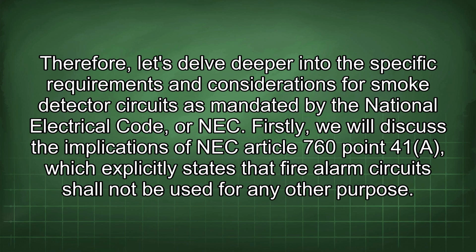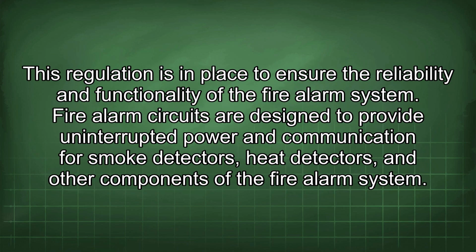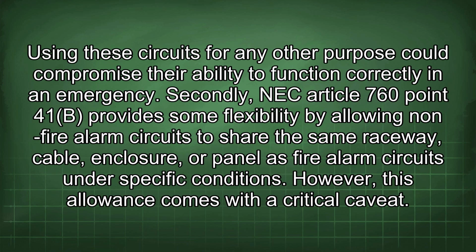Firstly, we will discuss the implications of NEC Article 760.41(a), which explicitly states that fire alarm circuits shall not be used for any other purpose. This regulation is in place to ensure the reliability and functionality of the fire alarm system. Fire alarm circuits are designed to provide uninterrupted power and communication for smoke detectors, heat detectors, and other components of the fire alarm system. Using these circuits for any other purpose could compromise their ability to function correctly in an emergency.